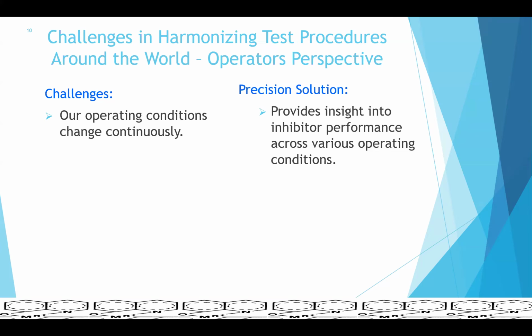As long as the operating conditions are within a certain operating envelope, we can consider that the operating conditions are stable. Again, integrity operating window is promoted by API 581 standard. So having a precision statement helps us not to react too much to the changes in the operating conditions.